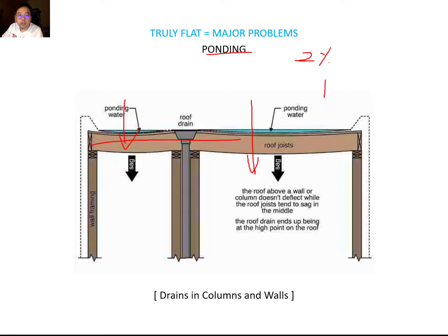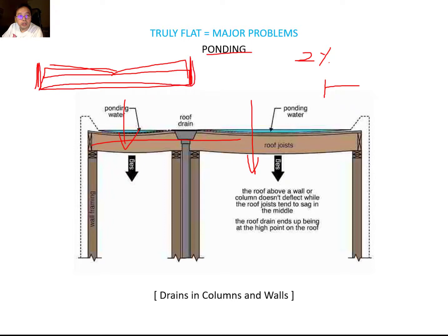So for this reason, I ask you to provide 2% slope over this flat roof. So when you see the outside, this is your design, making 2% here, 2% here, and outside you can simply cover the edge, right? So from the outside you can only see the flat roof, but inside of this cover edge you have this actual slope for the drainage of the water.